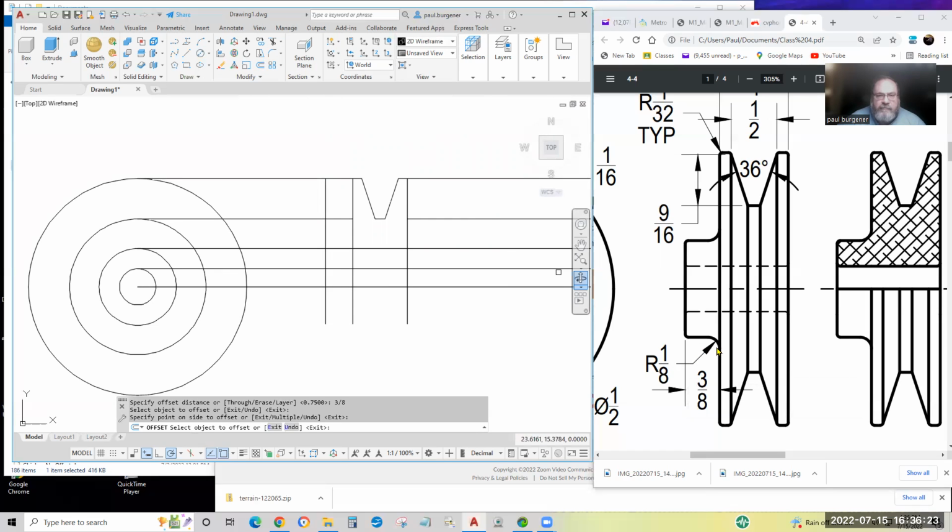There's 2 radii to apply. And remember here at the bottom, right, I'm sorry, the hidden line there, right there, that's a 0 radius. So I don't know whether to take advantage of the polyline command. Oh, and these are 0 radius too. I think I better fillet each corner individually. 1, 2, 3, 4, 5. Yeah. Fillet 5 corners individually and change the radius setting and fillet the 6th one here. Right? Yeah. Leaving these 2 corners at the bottom at 0 radius.